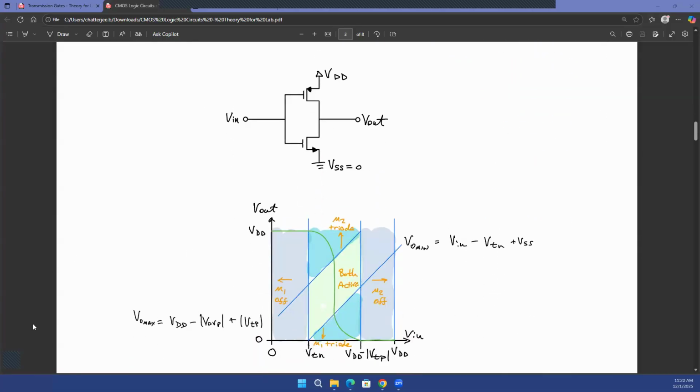So something interesting about digital circuits, for example, if you think about the digital inverter over here, as you are increasing your Vin, so let's say I want to draw the VTC of the digital inverter, and I want to understand which region the transistors are in a little bit more detail. So I have my Vin, and I'm increasing my Vin in this direction, and the y-axis is my Vout. Of course, if my input voltage is zero, this transistor is completely turned off, and the capacitor at the output gets charged.